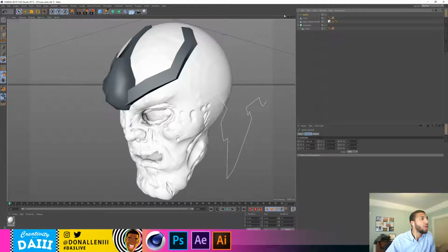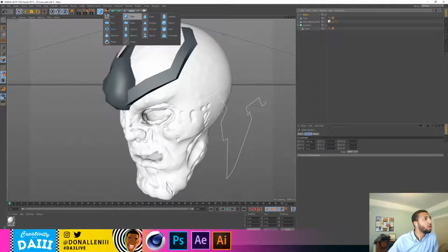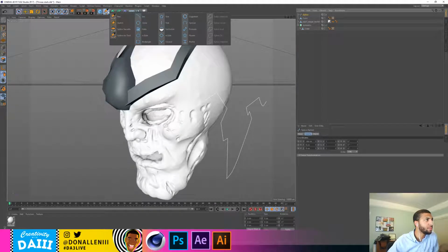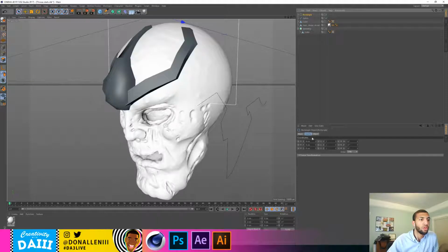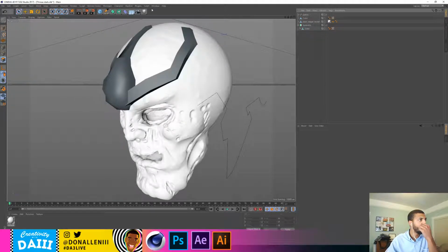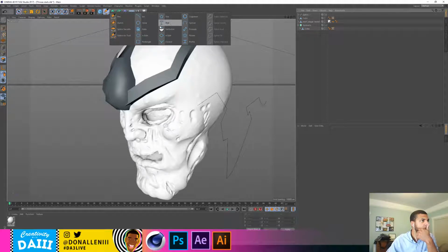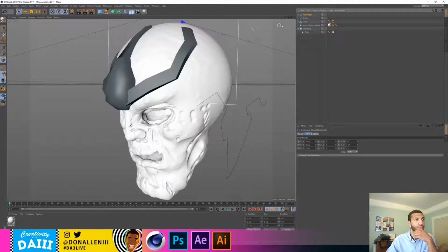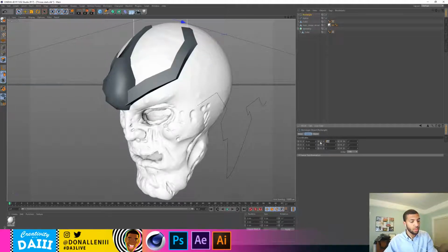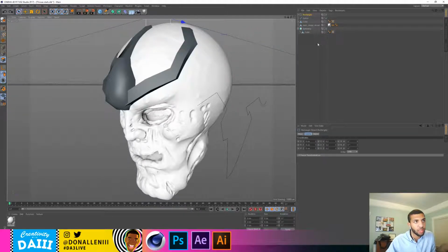What we're going to do with this shape is sweep a hard object on this. So I'm going to use a hard rectangle with a much tinier axis. Actually, delete that one. I'm going to go to this tool and do... Oh no, we can do it. We'll do rectangle. And then we'll change the scale quite a bit. So let's just do 0.2 by 0.2 by 0.2. All right, so it's just like a little tiny square. We'll make it tinier in a second.